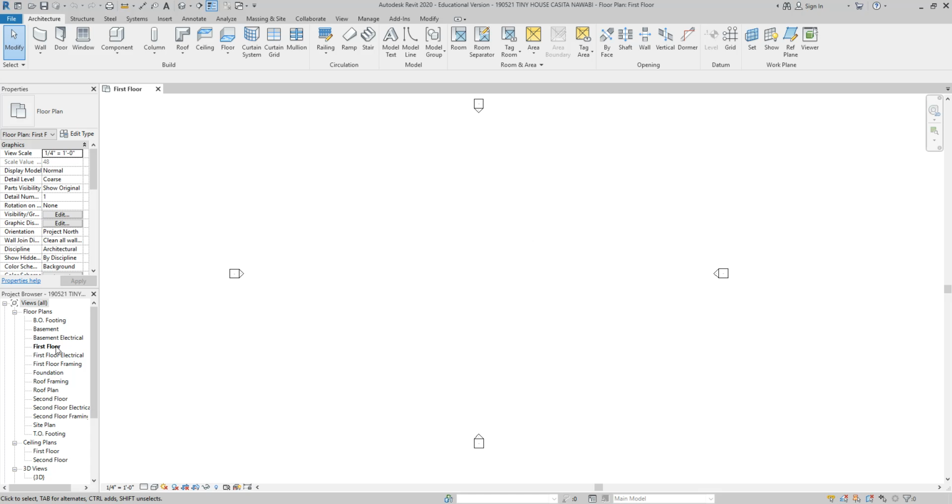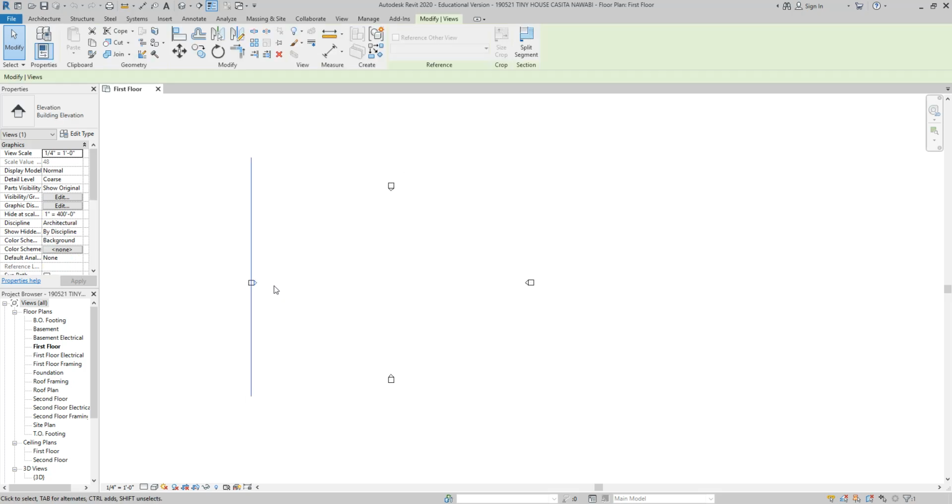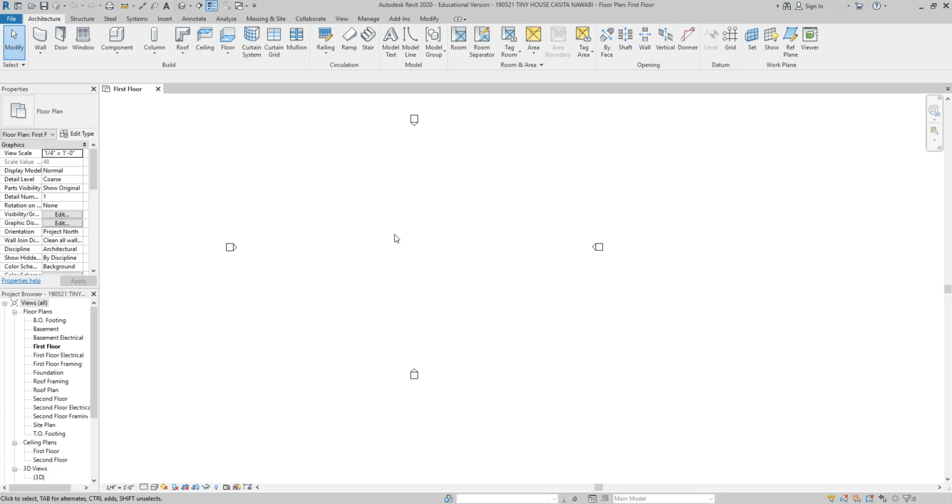We started in our first floor. And what are these again? Do you guys remember what these little triangles are? We did for just a moment. We're talking about where to draw. Yep, so these are our elevation markers. So essentially, this is a camera that will be looking at this face of the house. This is a camera that's looking at this elevation of the house. Okay, so that's why when we first open up a file, it's best to draw in here so that our cameras can see where we're drawing. Okay.